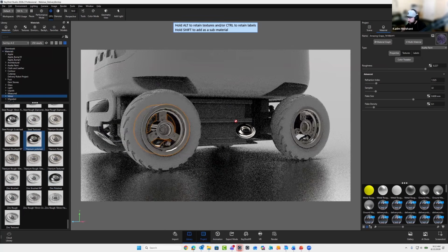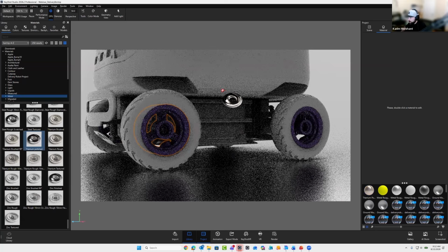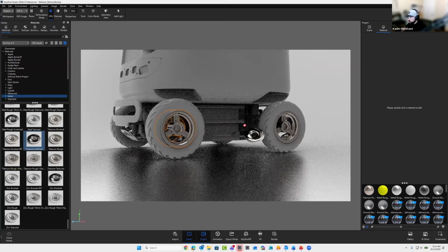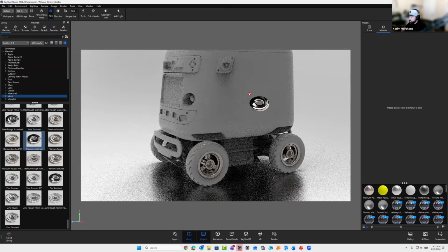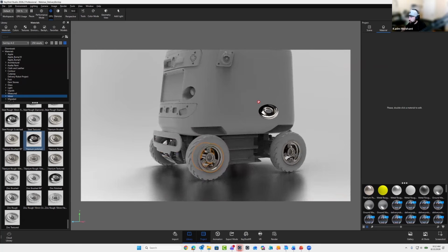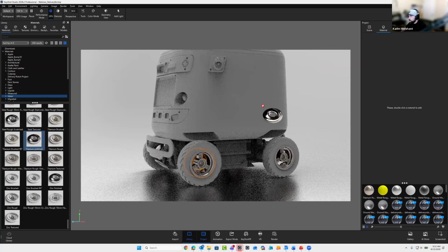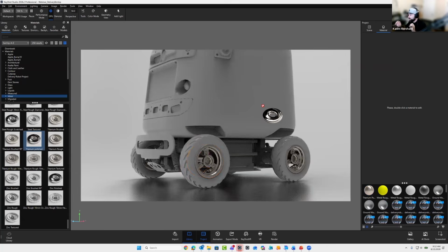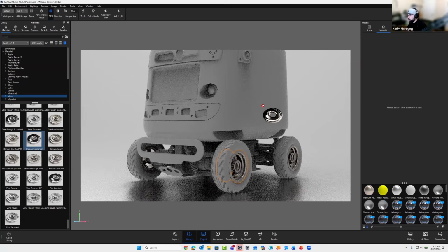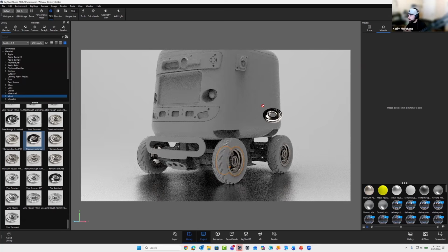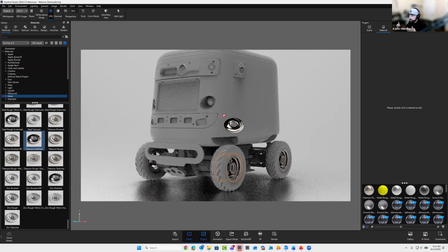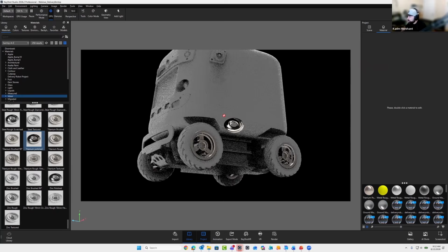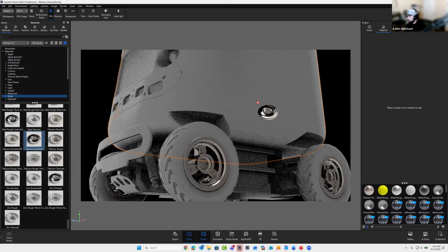If I zoom in here on the hubs, you'll notice that the actual lugs themselves are part of the hub itself. So I'm going to go ahead and use a tool to split those off. If I right click my body that I have selected here, we have two tools. We have split separate objects and split object surfaces. So split object surfaces essentially lets you just pull a face off of your object rather than splitting the entirety of that object. That's useful if you want to apply a specific material to one side, maybe, and not the other, or you're dealing with logos or some sort of graphic that you don't want to wrap around a radius or something like that. That's a very useful tool. But in this case, we're going to use the split separate objects.